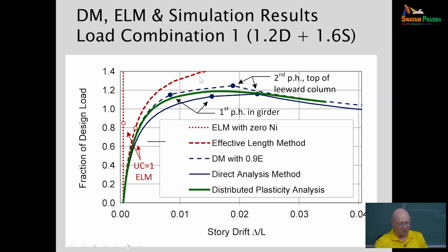So you can see that curve is going a bit higher than what I showed you for the second order elastic curve in Mastan a minute ago. Okay, and then, let me think here. Yes. All right. So the solid purple curve is the one we just generated, and the first circular symbol there on that curve is where we form the first plastic hinge. Gets a little flatter there. We form the second plastic hinge, and then we're going into post peak, where the frame is not going to be able to take any more load.